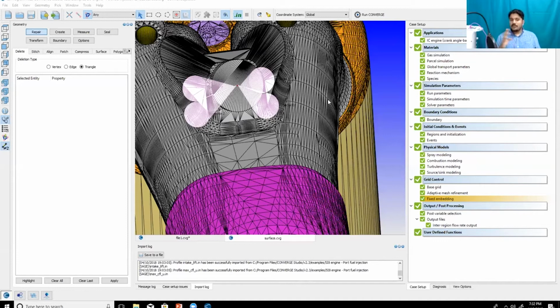So there are 2 ways to do it. One is turning off AMR, which would take a hell of a lot of time, but then you keep on reducing the base grid, and then hopefully you get your results. But even in that, you can actually get into an issue. As you know, you're using a turbulence model, right? And whenever you use a turbulence model, you have to use the right law of the wall boundary condition, which, depending upon the turbulence model, if it's a high Reynolds number model, you cannot have a lot of mesh refinement near the wall. I'm hoping you know that.